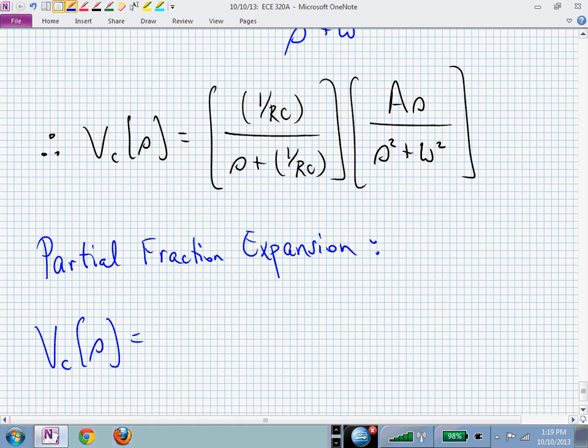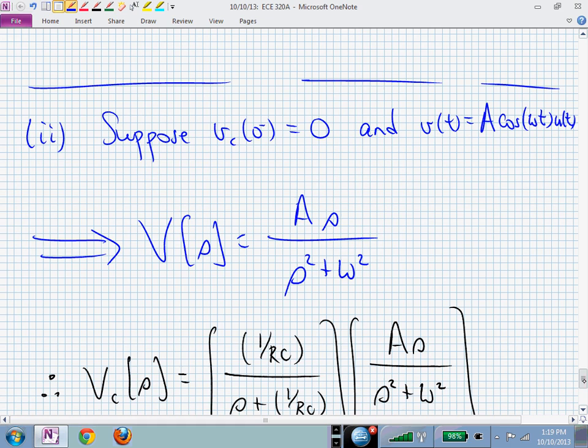And what else? What's that S plus 1 over RC producing in the time domain? It's going to get an exponential damping, isn't it? An exponential decay towards our sinusoidal steady state. Because we're not going to quit, are we? If we're shaking it, we just keep shaking. That's what V of t said. Once we start at time 0, we don't stop shaking. So that system will just start getting into a sinusoidal steady state behavior at a frequency of omega.